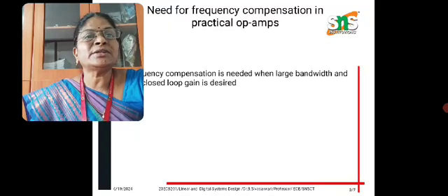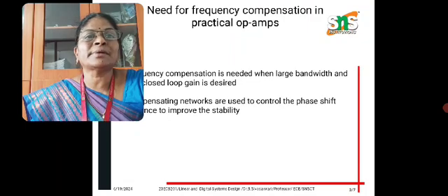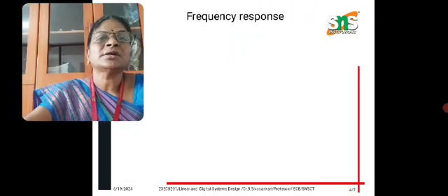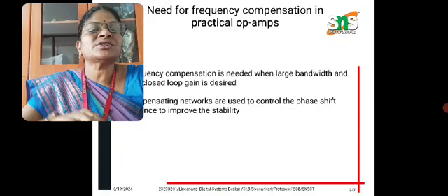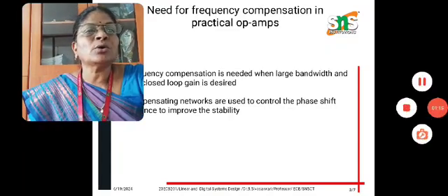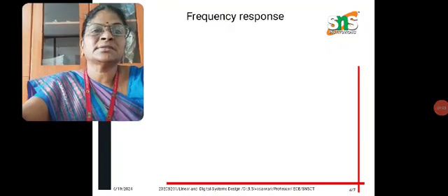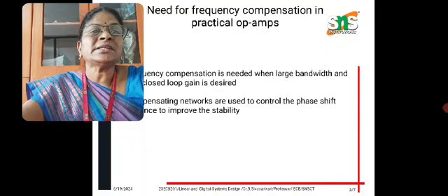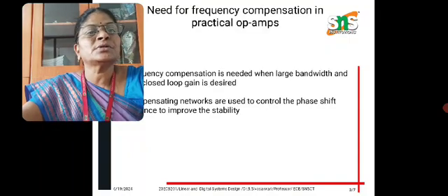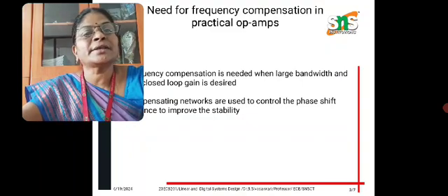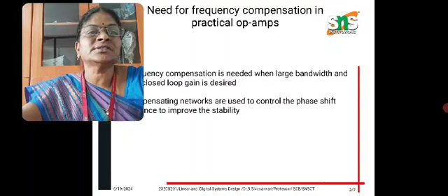So what is the need of frequency compensation in practical op-amps? Frequency compensation is needed when large bandwidth and closed loop gain is desired. The compensating networks are used to control the phase shift and to improve the stability of the circuit.